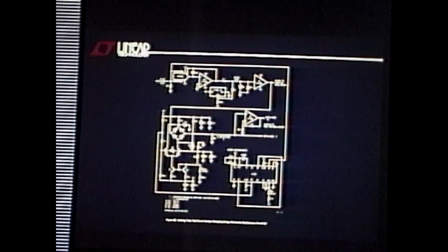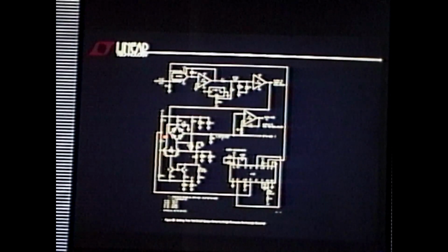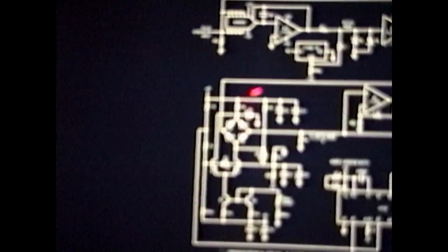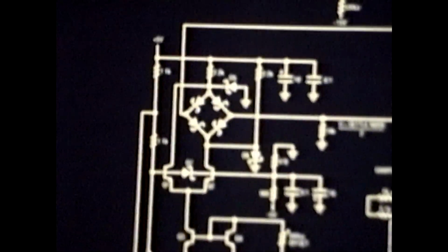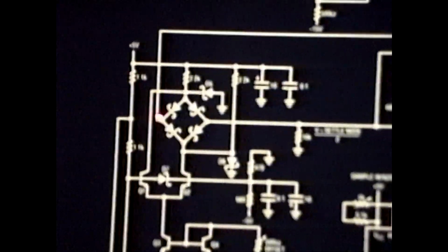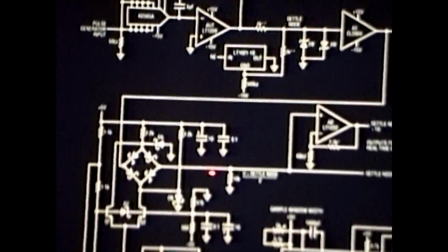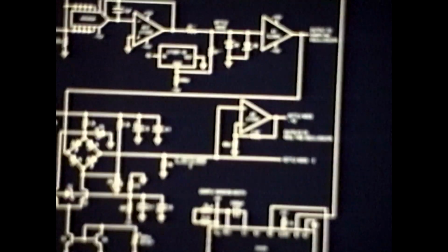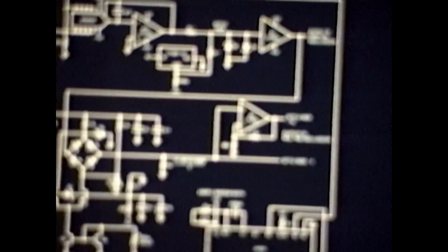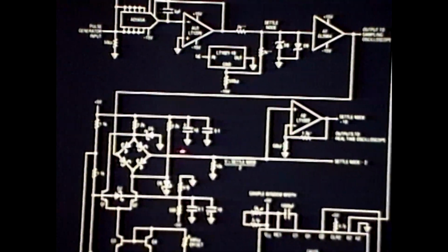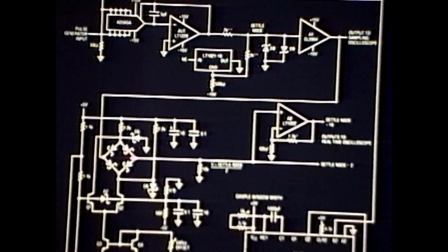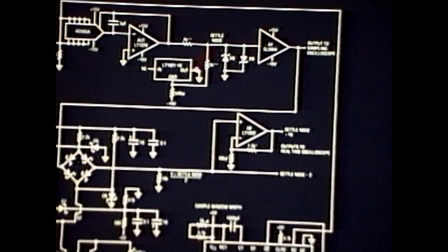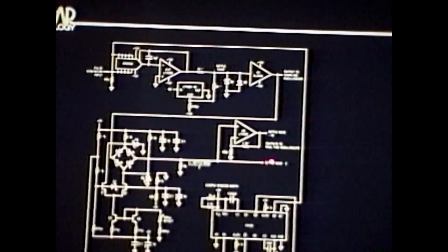The way this thing works, at the same time that you bang the D to A, you hit this one shot. So you generate a delay, and you open up the sampling bridge. So all the slewing and horrible stuff that's going on over here sits on this side of the bridge, doesn't appear there. After some adjustable delay time, so you're basically going to peel back the time in negative fashion, you're going to catch the trailing edge of the settling right there. You're going to let the bridge close. Okay, so you clip the waveform in amplitude and in time.